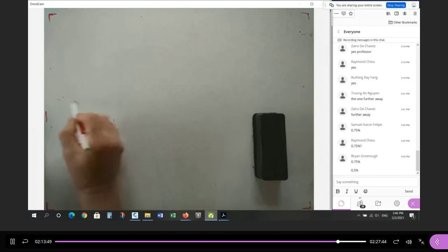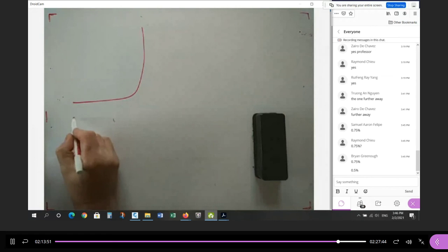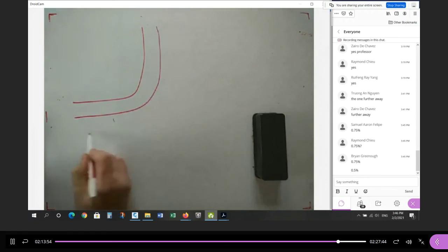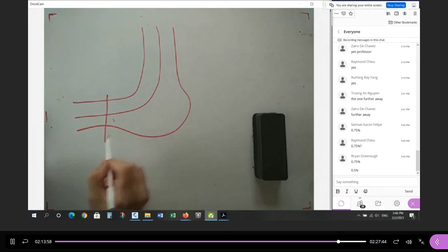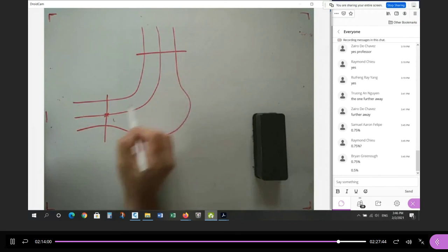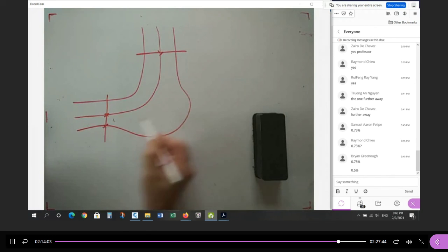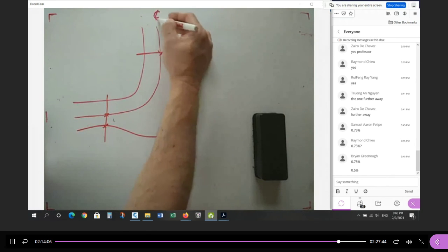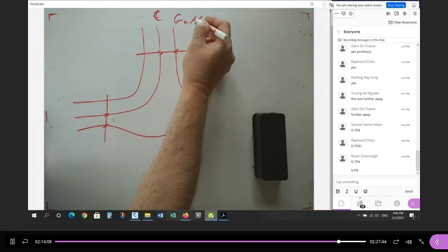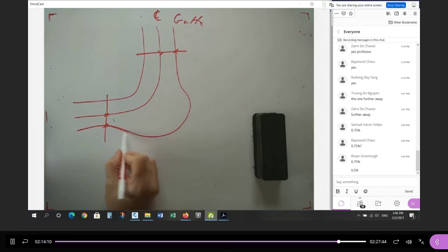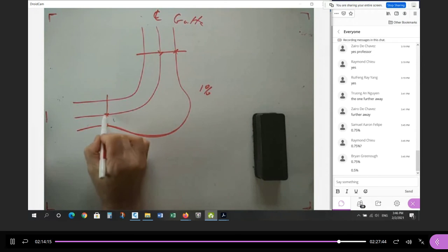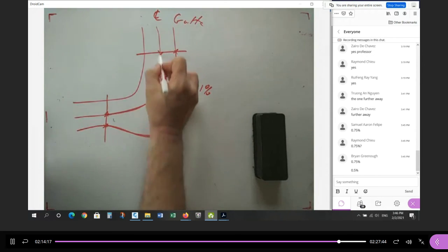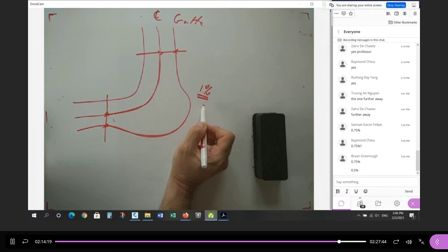So if you remember last year, we had an edge of pavement, a center line, and a gutter. And where the standard section ends, this is the beginning of the zone, this is the end of the zone, this is the beginning of the zone, this is the end of the zone. This is the center line, this is the gutter. The slope from here all the way along here had to be minimum 1%, which means the slope from here to here had to be designed steeper. Remember, it was steeper. And we had to do a calculation.